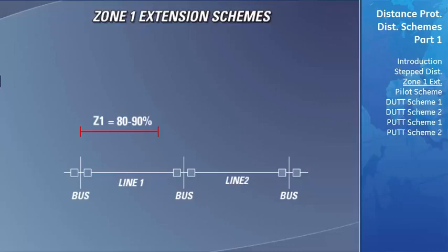If the fault was permanent and reappeared after the reclosing, but was not located in the new shortened Zone 1 protected area, the D60 would not pick this up for a second time in Zone 1 and not trip to try to clear the fault. If the fault fell inside the transmission line's end zone area, the permanent fault would then be cleared by the Zone 2 protection after the set time delay.